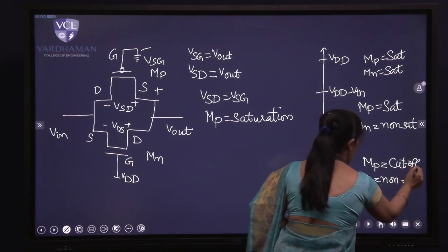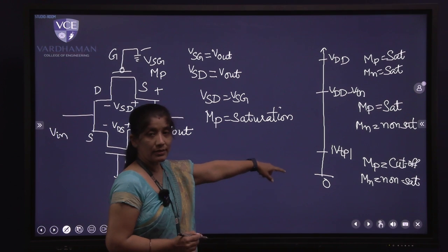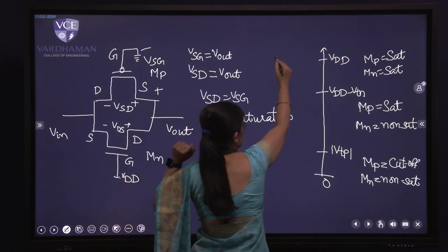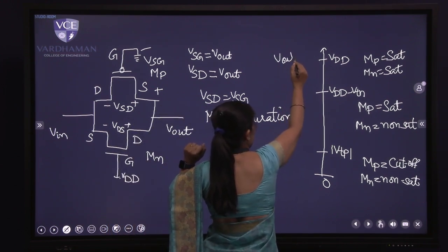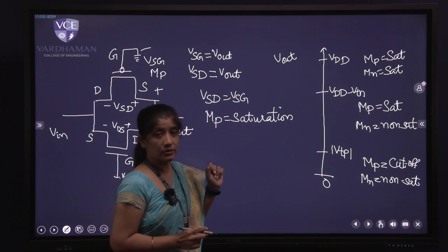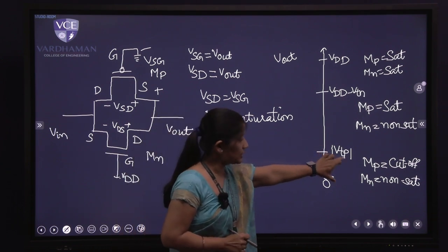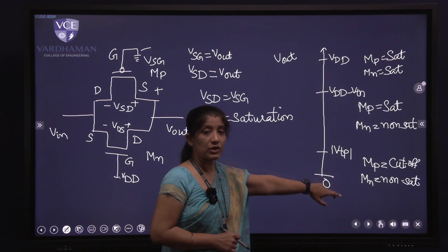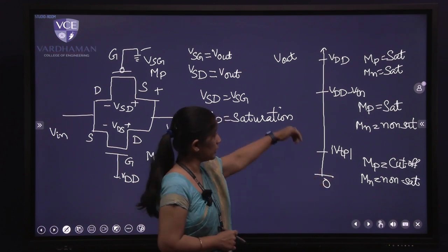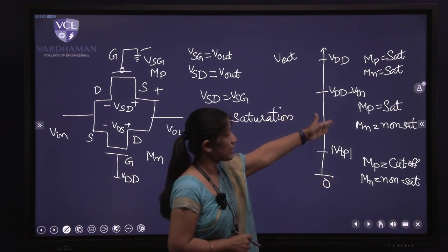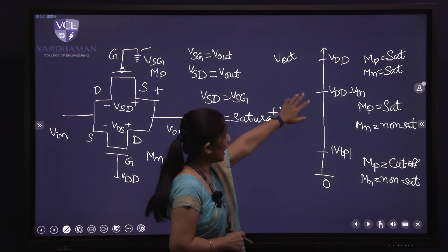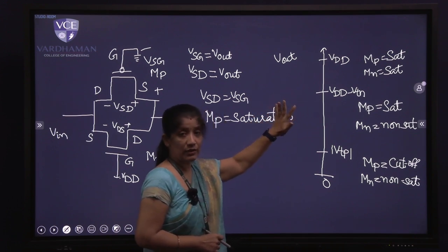So this is how, if you see the characteristic curve here of the Vout, this is for the output voltage. The same we have done for logic 1 transfer. You see that here I have 0, VTP. Within this range, MP is in cutoff region, Mn is in non-saturation region. Beyond this, Mn is in non-saturation, MP is saturation. And for the first two, both are in saturation.